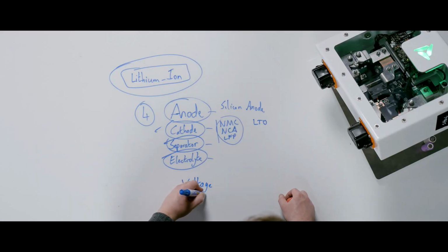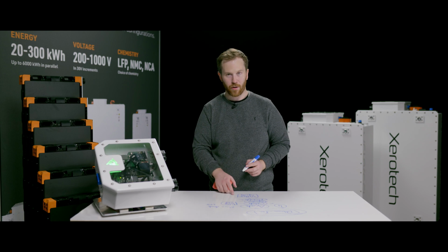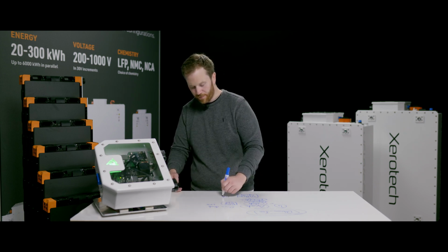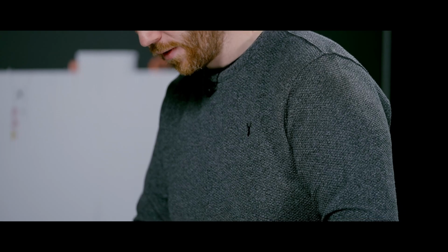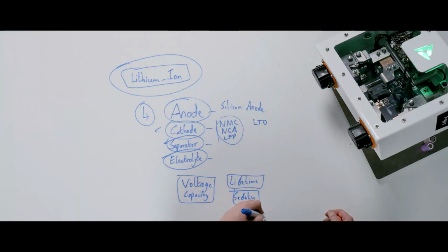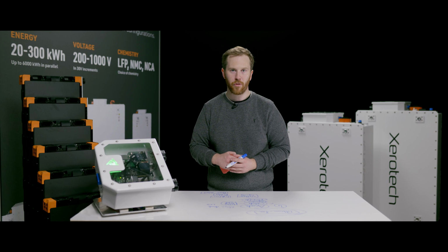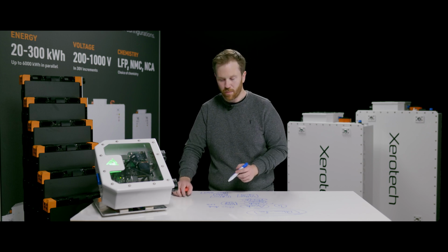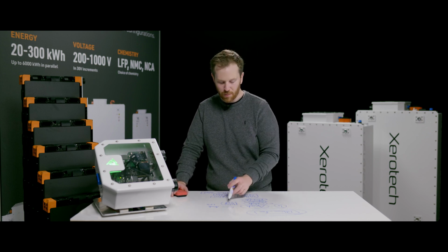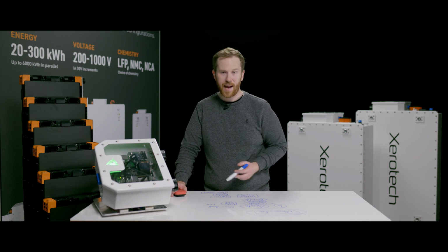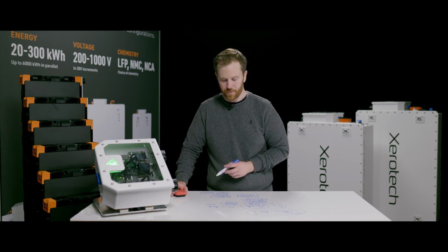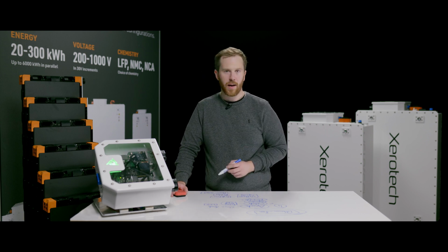And generally speaking, the things that you care about in the battery are the voltage and its capacity. There are some other things in here that may matter as well, that is the lifetime and potentially safety considerations, as well as power output. Some of these chemistries are slightly different and they're better at one thing versus another. So we're going to be taking a deep dive between the 3 most common commercial chemistries on the market today. So that's NMC, NCA, and LFP. And we might do a little note on LTO.